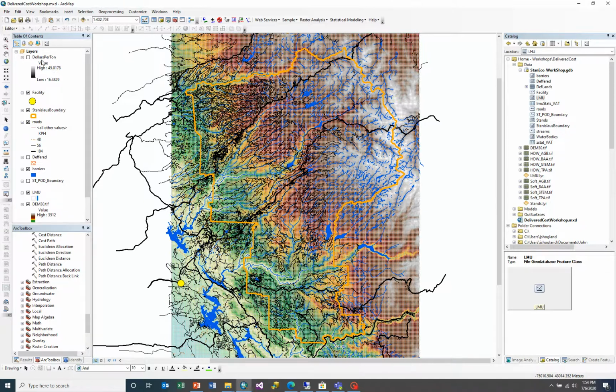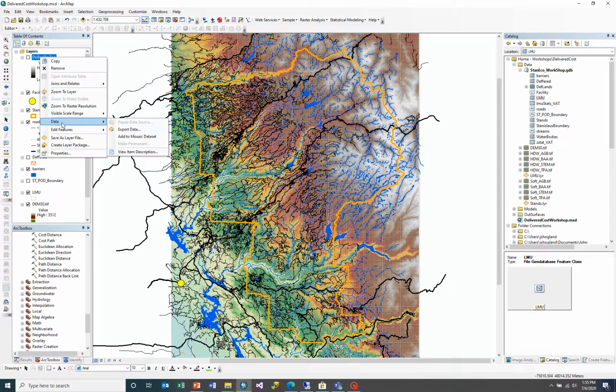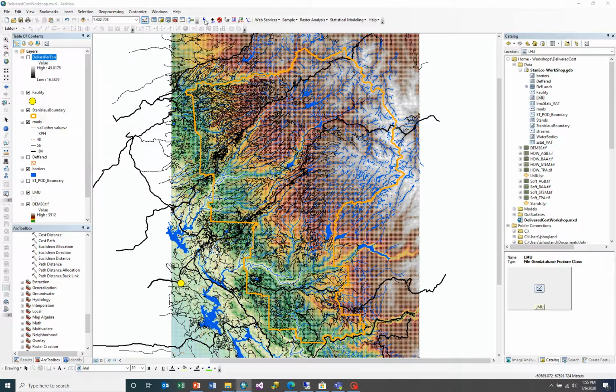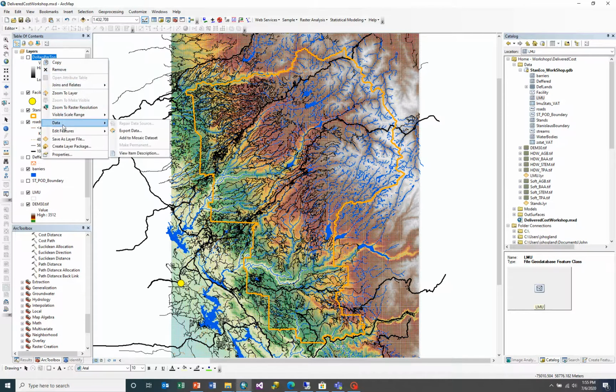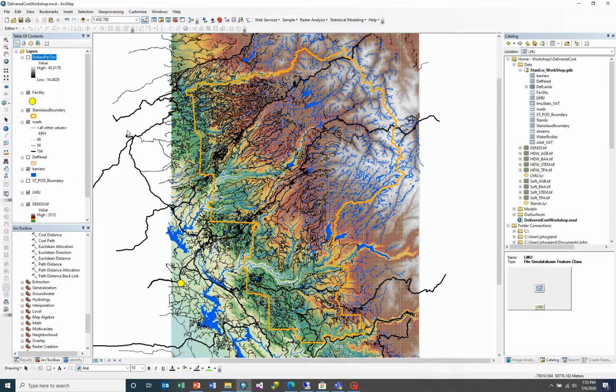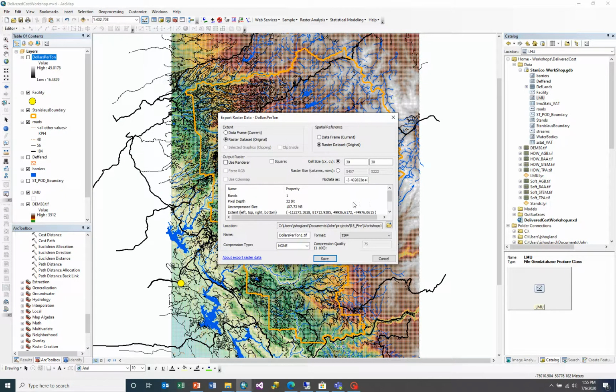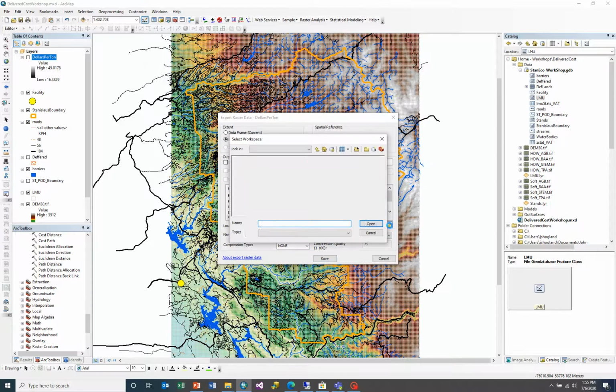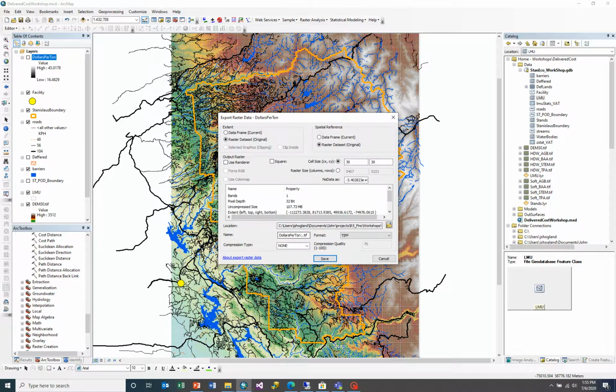Now, the output of this is created as a function raster, meaning it's not stored permanently to disk. So at this point in time, we're going to go ahead and permanently store it to disk. Now we can use Esri's save function, or we can use the save function I have created to save this raster to disk. And in this case, I'm just going to go ahead and export it using Esri's save function as a surface. We need to specify an output location, and I'm going to specify our travel times 1, and we're going to store it as a TIFF.